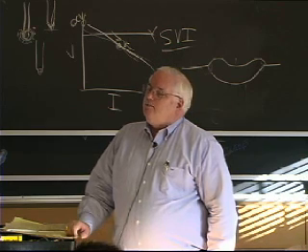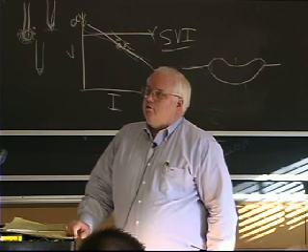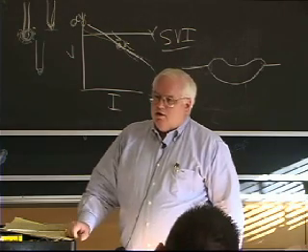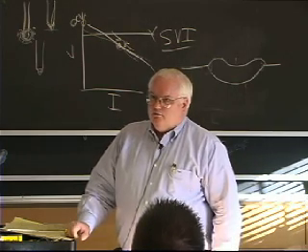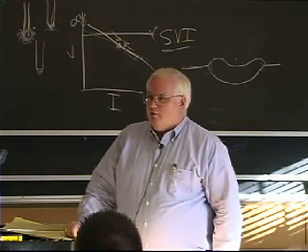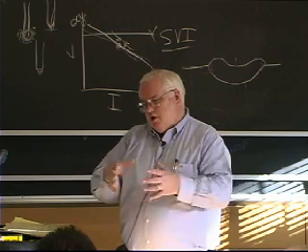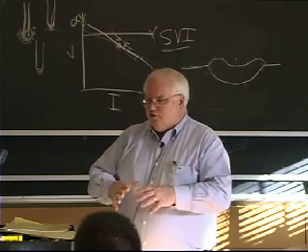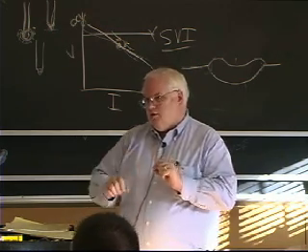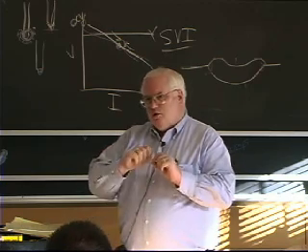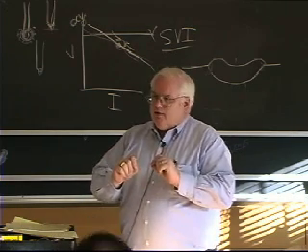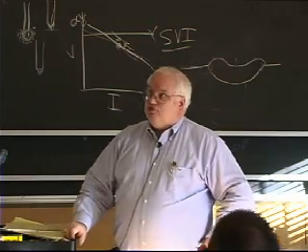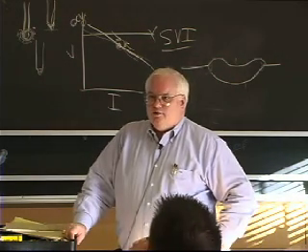Oh, I had a pipeline failure in Texas where they were doing submerged arc welding in the pipe mill, and the undercut was only about a ½ millimeter, but the code only allows about a ¼ millimeter, because it turns out the pipelines change the pressure and you get a fatigue crack. And this thing had been in service for over 20 years, and it finally developed a fatigue crack at this thing. There was some corrosion going on too, which is what the fight was all about. But it finally split open and let go 16,000 gallons of gasoline into this farmer's field.